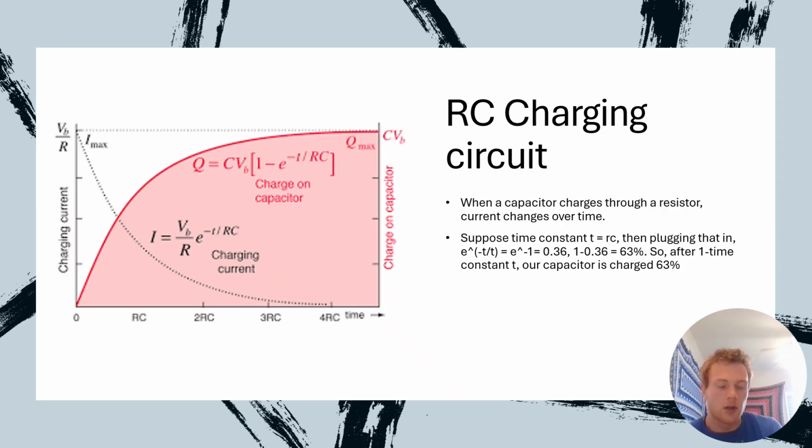The way a capacitor's equivalent capacitance works is that if it's in series, it's like a resistor in parallel, where it's 1 over C. And if it's in parallel, then it's like a resistor in series, where we just add them. So that's the general rule.